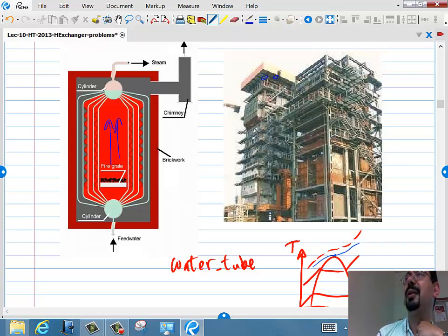Potential energy, gravity. Gravity and potential energy of getting it back down. No, it's not gravity. It's because when they start the operation, it gets very hot, it expands. So if it's sitting on the floor and expands, it can pull from its frame. But if they are hanging it, it can expand freely. They say it's like 1 foot between when it's empty and when it's full. And also the water, when you fill it with water, it also expands a little bit.